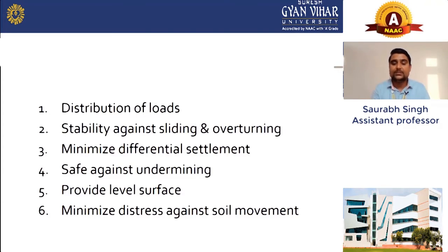Second one is stability against sliding and overturning. Whichever foundation you make, it should be stable, and it should also resist sliding and overturning. Many times, as in the previous lecture, a structure collapsed due to overturning and sliding of the soil. This is a very important thing.